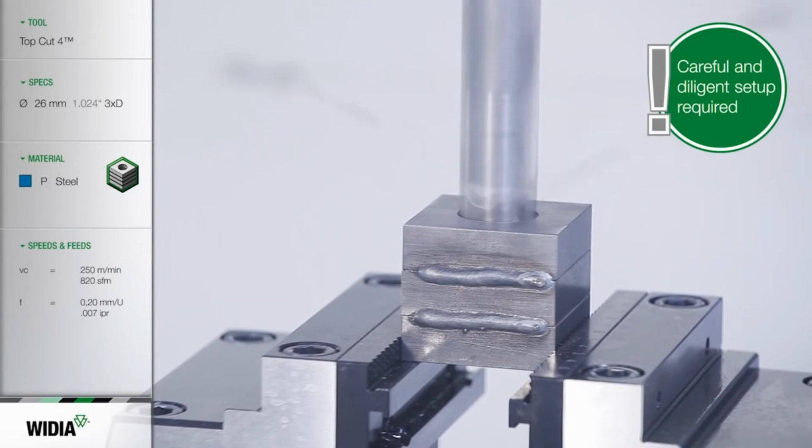In some cases, you can use indexable drills also for stack materials drilling. So when one component is laid on another component, but they need to be clamped in a very rigid way, like here, they almost can be said they are braced, and the gap between them should not exceed about 1.5 millimeters, because when you use an indexable drill, a small or narrow disc goes out from the first component to the second, so in the space of this gap, and it can destroy the insert.